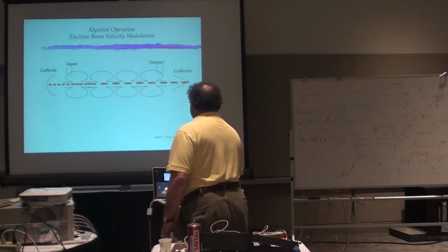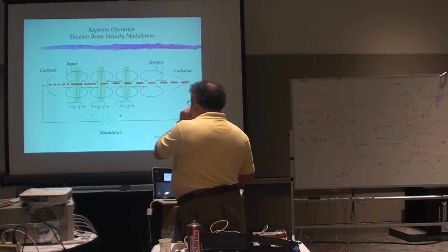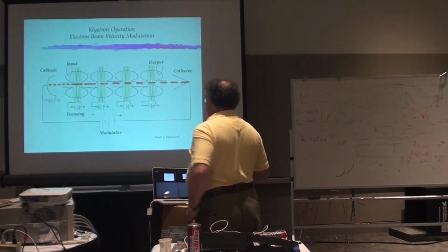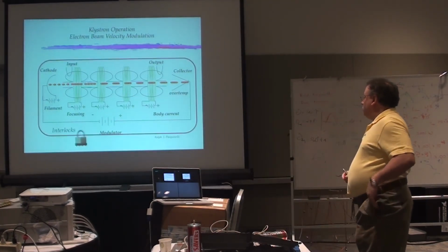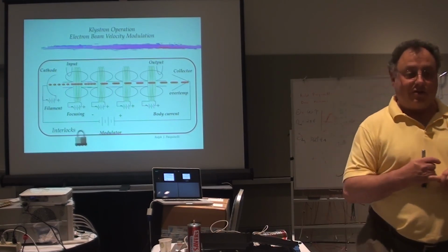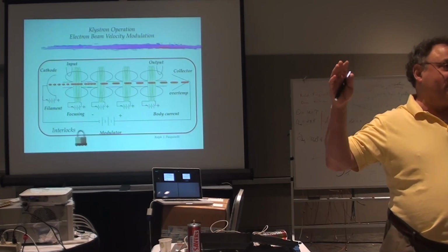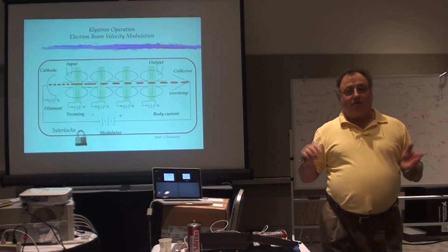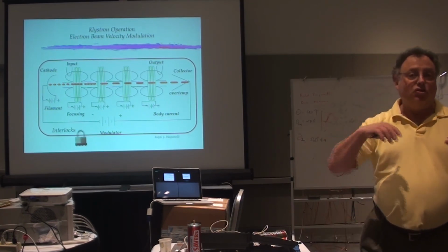Okay. But that's not all, of course. It takes a lot more in order to make all of this happen. You need a modulator, if it's a pulse system, to provide the voltage to get the electron beam going. In the case of our 12 megawatt klystron, that's about 180,000 volts, and it pulses on for on the order of 3 to 400 microseconds. The beam is actually good for only about 120 microseconds.